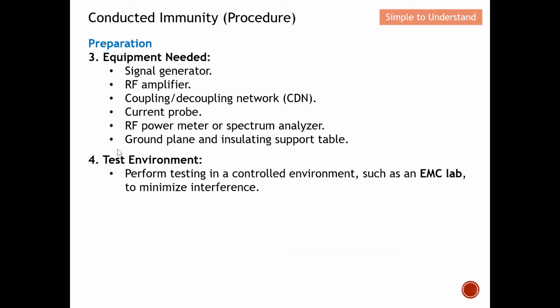About the test environment, although it's not necessary, we prefer to do this testing in a controlled environment, for example, in a shielded room, so as to minimize the interference. For example, noise can couple into the cable, and this can become an issue. Because of this, we prefer to do it in a shielded room. We minimize the interference as much as possible.